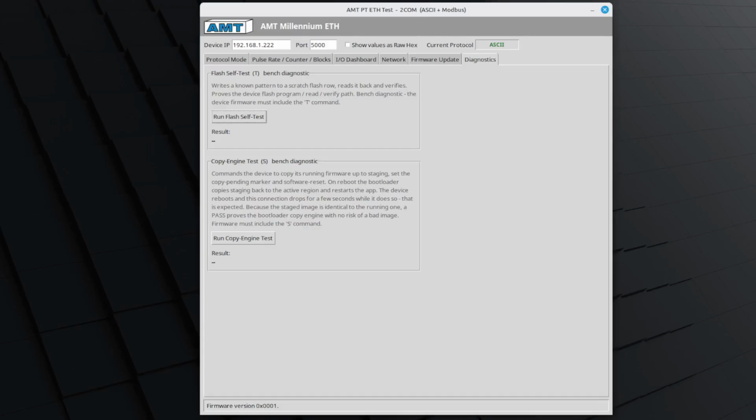That covers the pulse totalizing and rate, analog digital I/O, field calibration, protected counter, and firmware update, all over one Ethernet connection. The tester works a Modbus unit just as easily. It detects the active protocol the moment it connects and shows only the tabs that apply, so a Modbus unit brings up its own I/O, rate, and counter tabs.